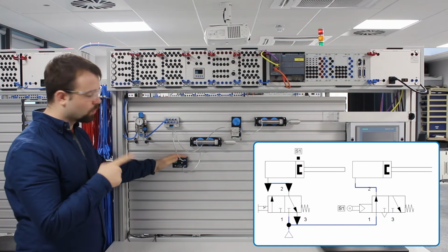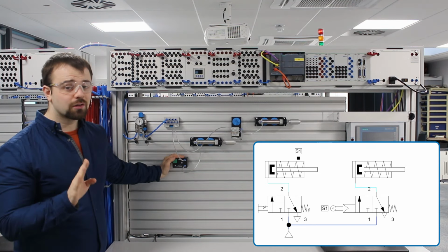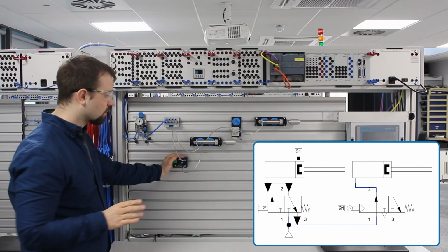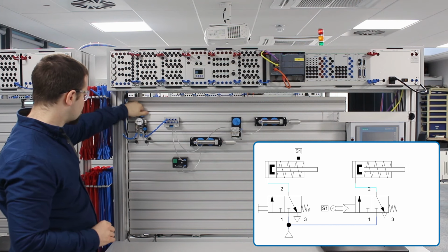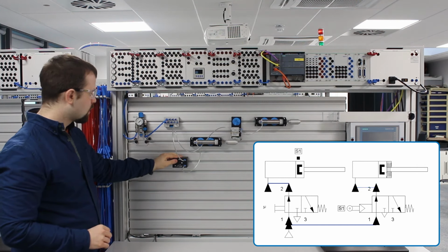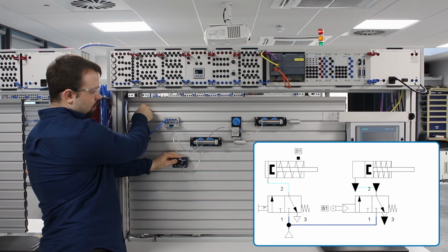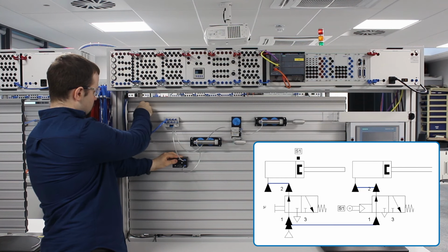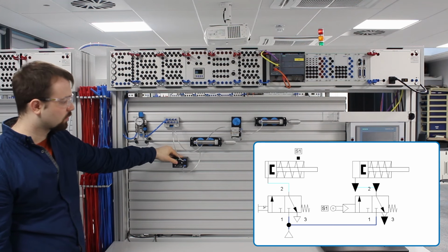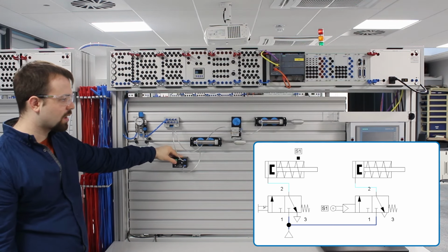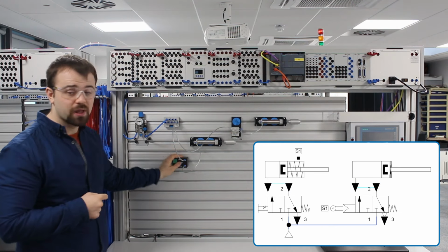Now it'll be quite quick, so here we go. It almost looks like it's happening at the same time, but I promise you it isn't. What I'll do is I'll just slow down the air supply a little bit and try. Here we go. And you should be able to see. Here we go. A triggers B. So A forward, B forward. A forward, B forward. You'll also notice that A starts to come back before B comes back.